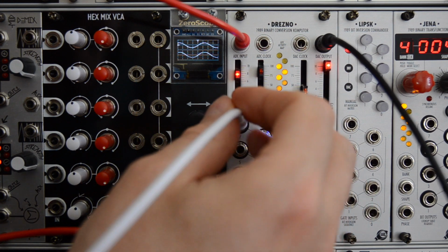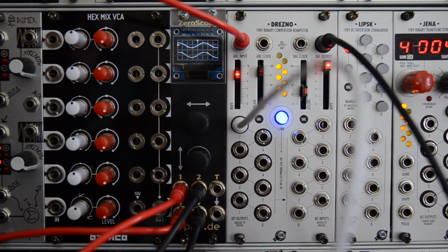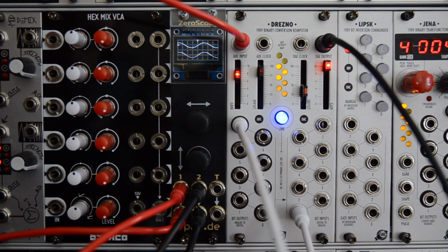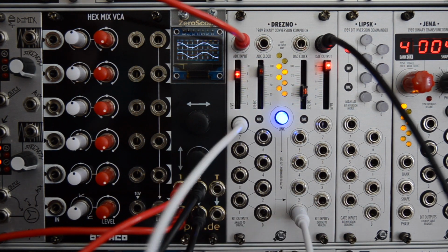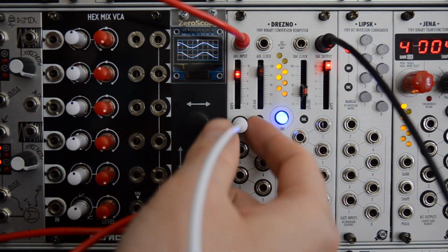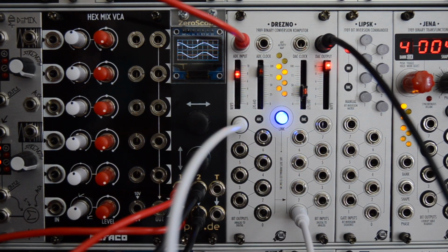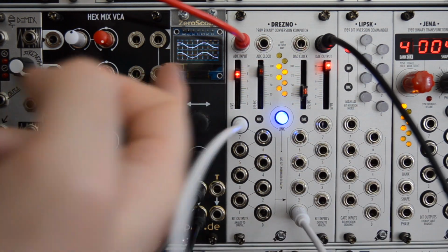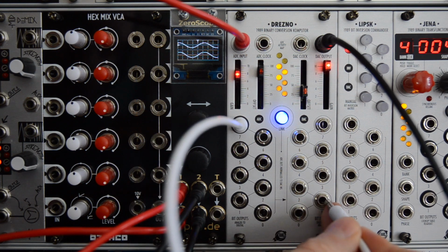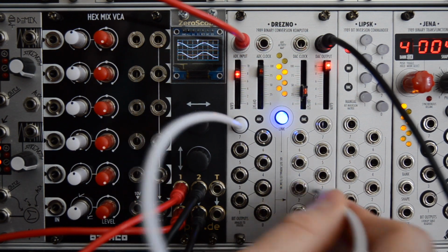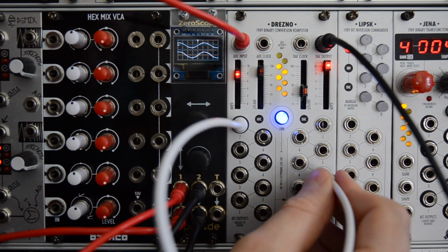Alternatively, if you patch the most significant bit output into the least significant bit input, you won't see much of a change, because even though it's changing really slowly, when we're not feeding this slow changing information into one of the most significant bits, we won't see much of a difference. But when we go up, you will see how there's something changing in the output wave.